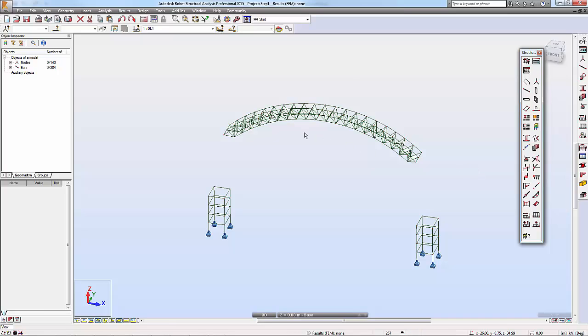So this is somehow like a structure where one is flying in the air and the other one is on the bottom of it, and once you apply the loading, this truss is going to open up because of a compatibility problem. You set up the compatibility relationship between these two joints. This joint moves and this joint will follow, as if these two are stitched together. So they are the same. No matter whether you put them together or not, they give you the same answer. So that's why you can run the analysis now.